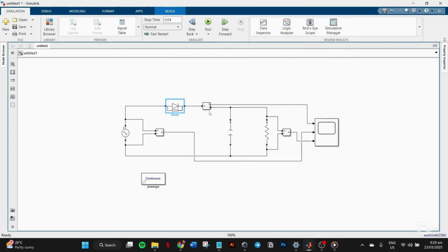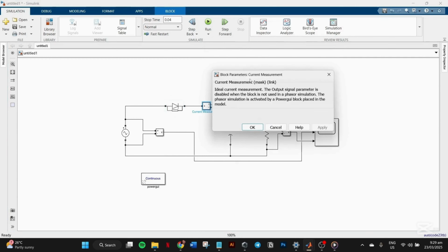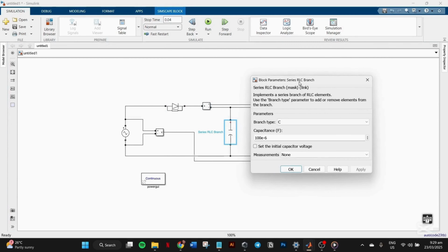Next, we have the capacitor or the C filter. The capacitor is placed in parallel to the resistive load to smooth out the pulsating DC. During the positive cycles, the capacitor charges to the peak voltage, and during the negative cycles, it discharges slowly, providing a more consistent DC output. This filtering process significantly reduces ripples and improves the quality of the DC output.